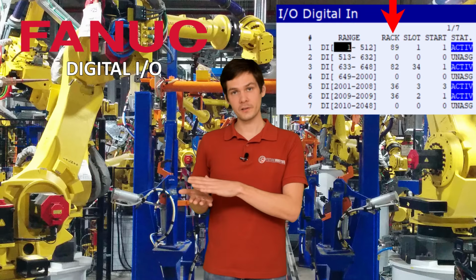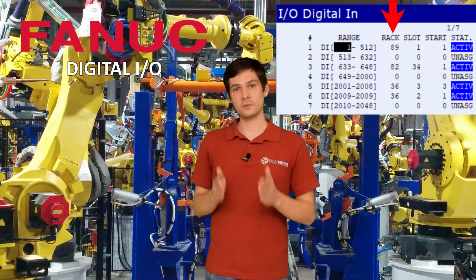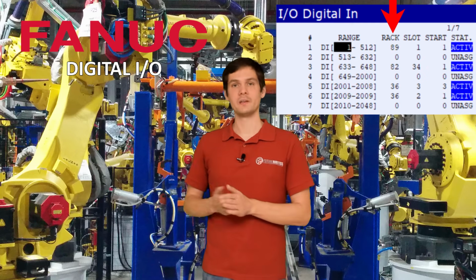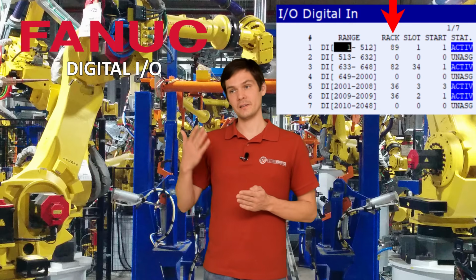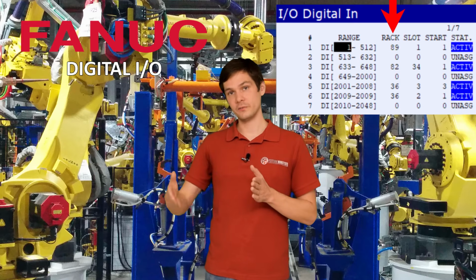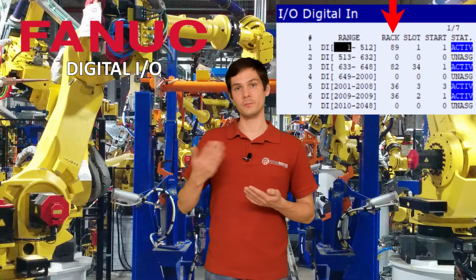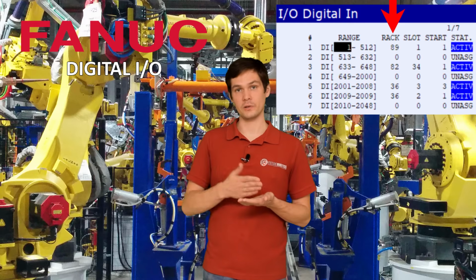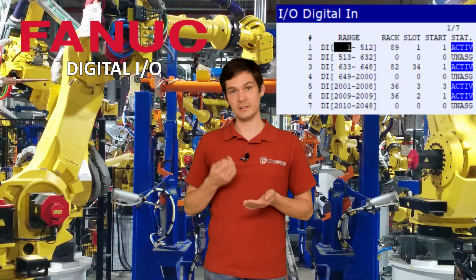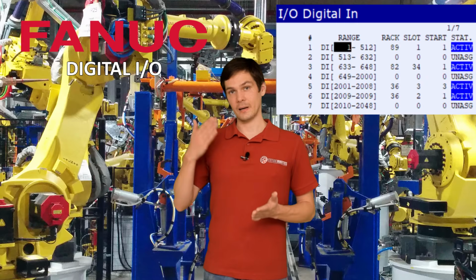So with the rack number, you're basically saying to the robot, hey, right now you're going to communicate with card number 89, Ethernet IP. Then the robot will know, okay, now I'm going to communicate with the cards. Now some of the cards can have one or more inputs or outputs, like basically one or more plugs that you can plug the cable in, the wires in, and so on. So there comes the slot.